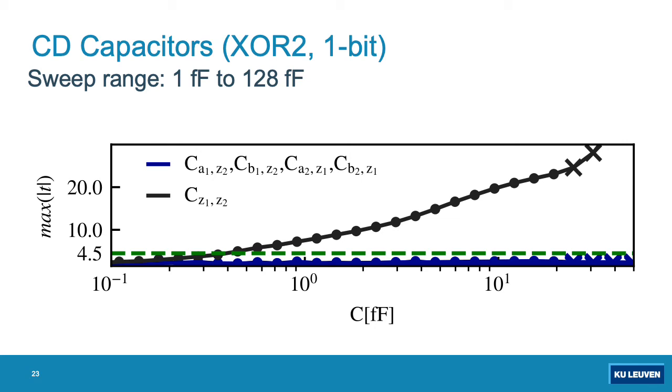And looking at this library documentation, we find pin capacitances to be of the order of several femtofarads. Therefore, we find the values of tens of femtofarads to be rather unlikely, and therefore we find that the risk of coupling capacitances causing this out-of-model leakage may be lower than previously thought.